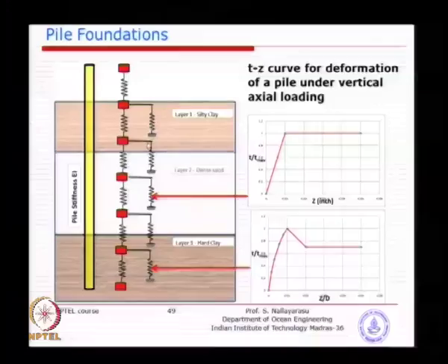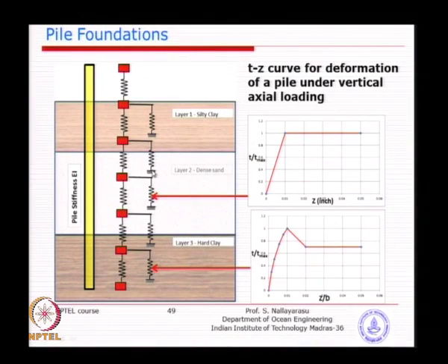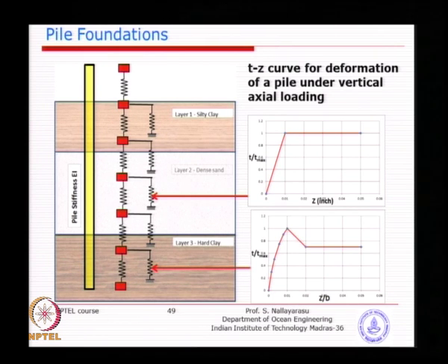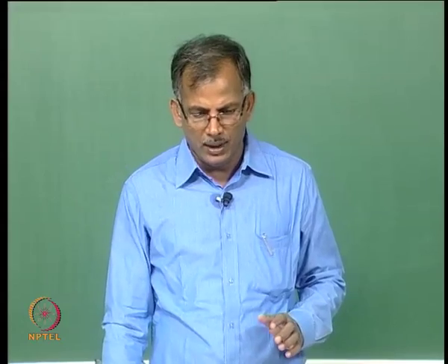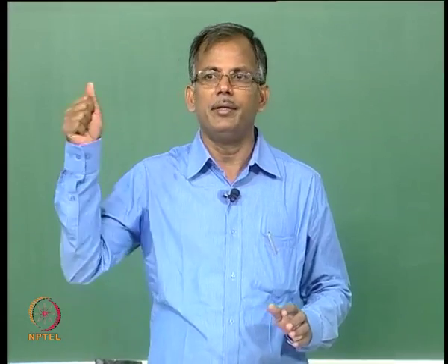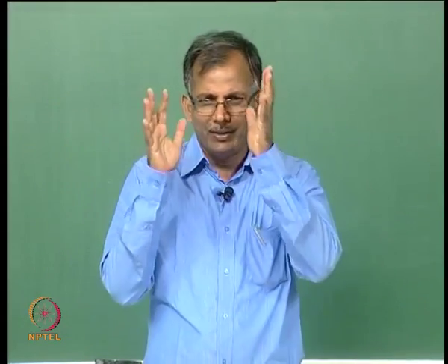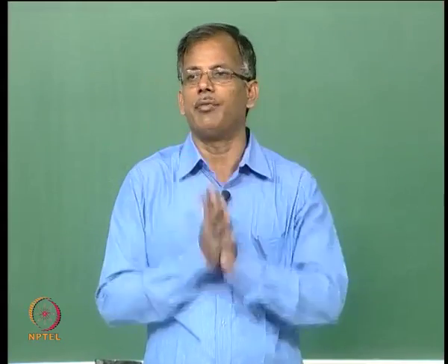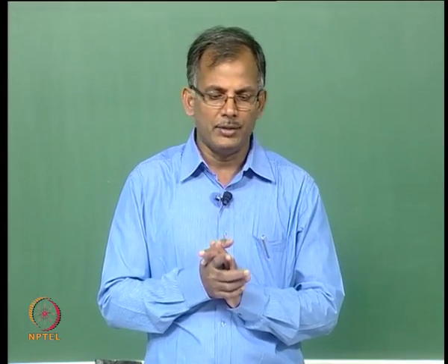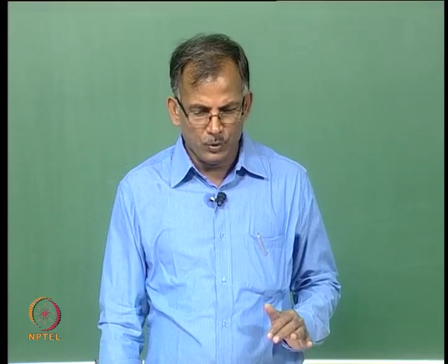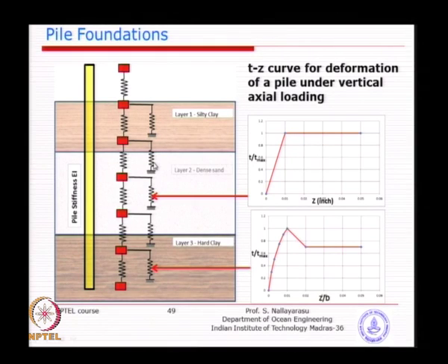So, you can see here at a little bit of distance away, 10% of the diameter, 20% of the diameter, the mobilization of the friction or the strength value from the pile to soil is going to be minimum. So, you can consider that soil as a rigid datum. So, the in-between soil is trying to behave as a shear failure. So, easy, you can understand. So, this spring value, the so-called frictional spring, is what we want to find out.